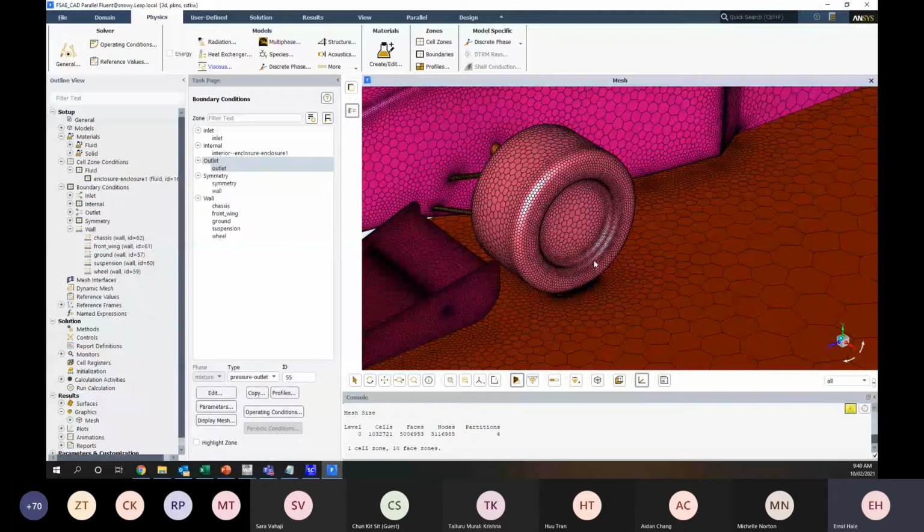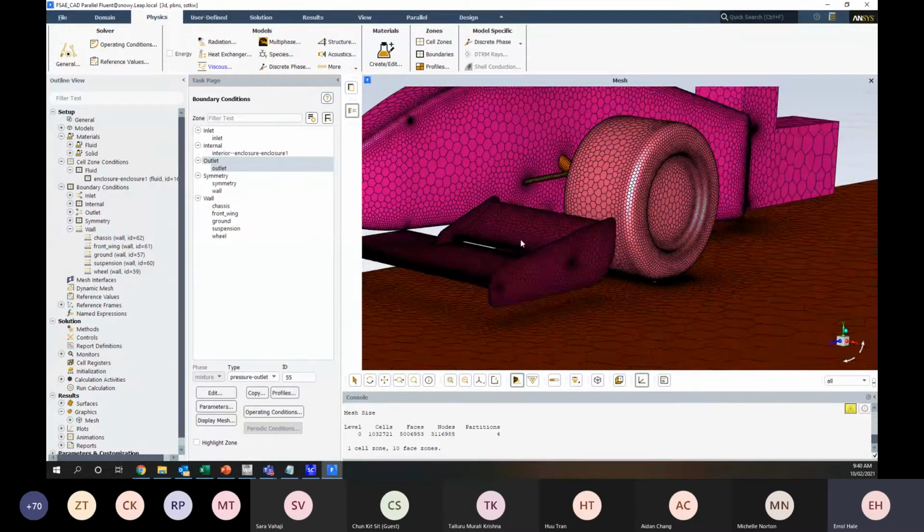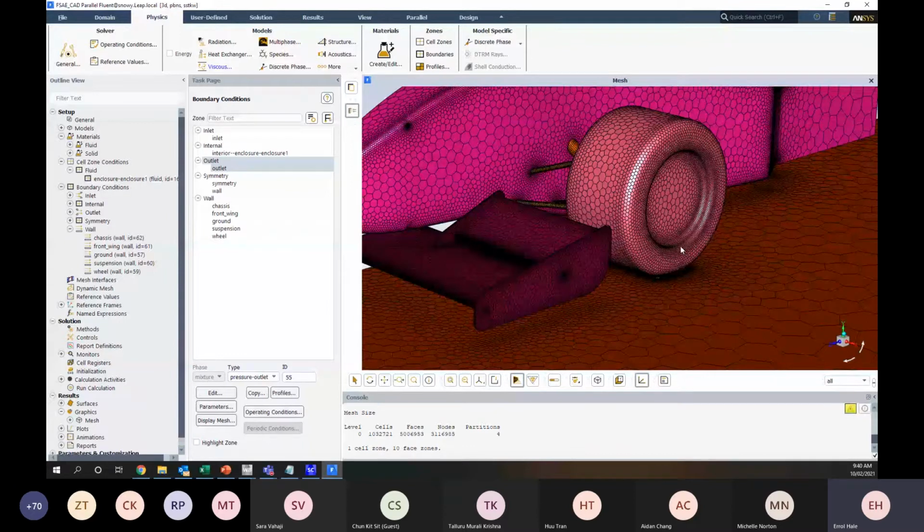It can be really important to have your tire shape be more accurate in terms of trying to understand what's happening to the flow in these areas. But it's always a toss-up. Do we need to go into that much detail? Can we do 10 different front wing iterations without having to change the front wheel shape and get a good understanding of the difference between the front wing designs, and still have a really good useful understanding of what's happening in that area without having to go to that much effort? It's always going to be a toss-up between accuracy and time spent on the simulation.